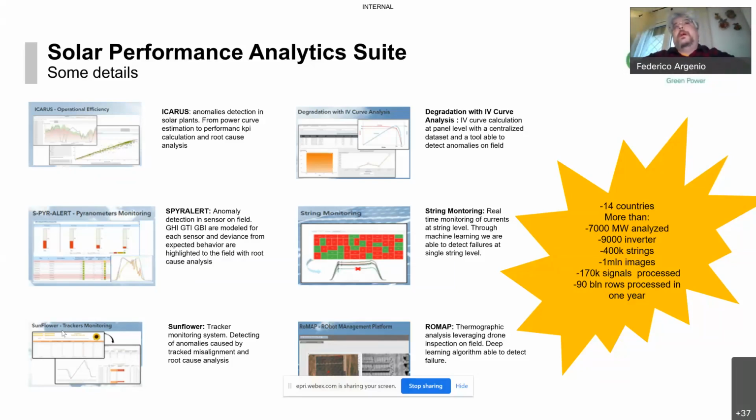that we use for the central inverter. It's a big inverter for which, for cost reasons, it's not required to have a one-to-one correspondence between current measurement sensors and single strings. This is very useful for very big solar plants, for which installing 100,000 sensors obviously costs too much in terms of installation and maintenance.